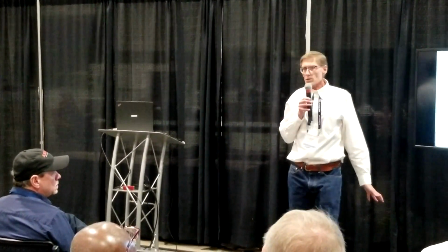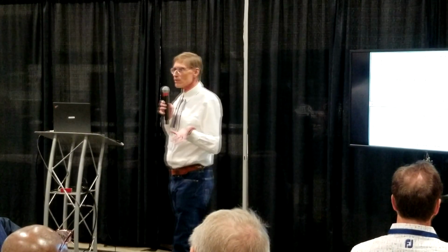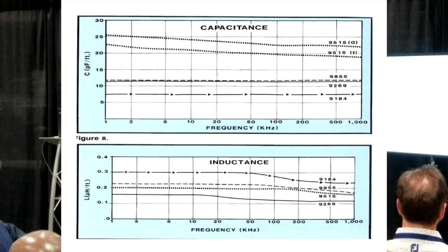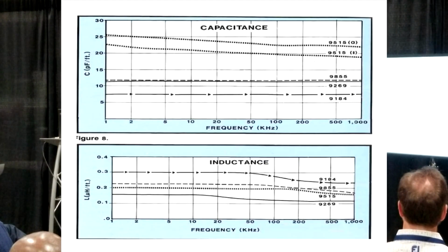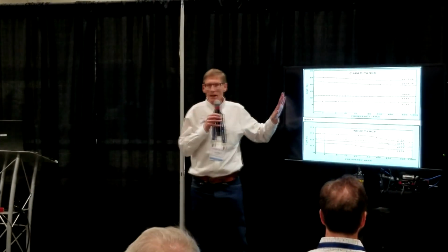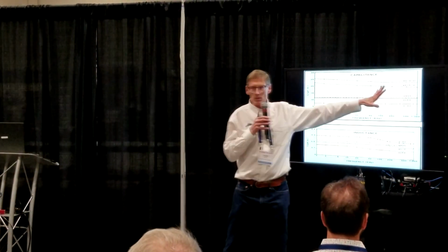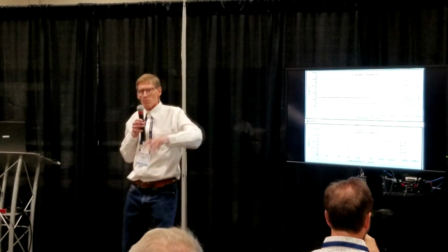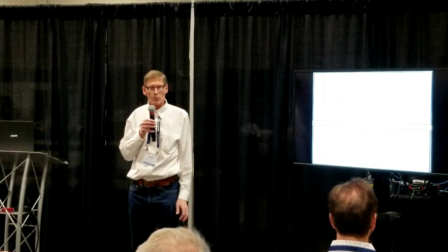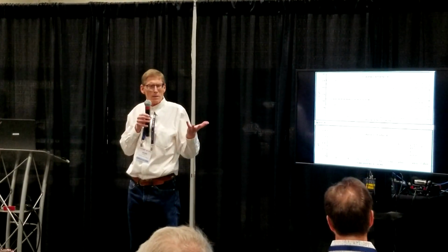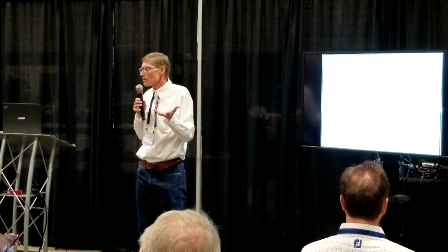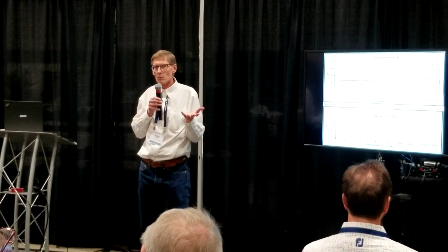If we look at our standard measurements for resistance, capacitance, inductance, when I'm measuring that cable at 6 gigahertz, 12 gigahertz, roughly 1 megahertz, what's the frequency point at which we measure the capacitance? Now this was actually swept capacitance to build these graphs, but in the Belden catalog, let's say you look up a capacitance on a cable and it says it's 17.3 picofarads, and you're looking at a MATV, CATV, high frequency coaxial cable. Where do you think they measure that capacitance? What frequency?